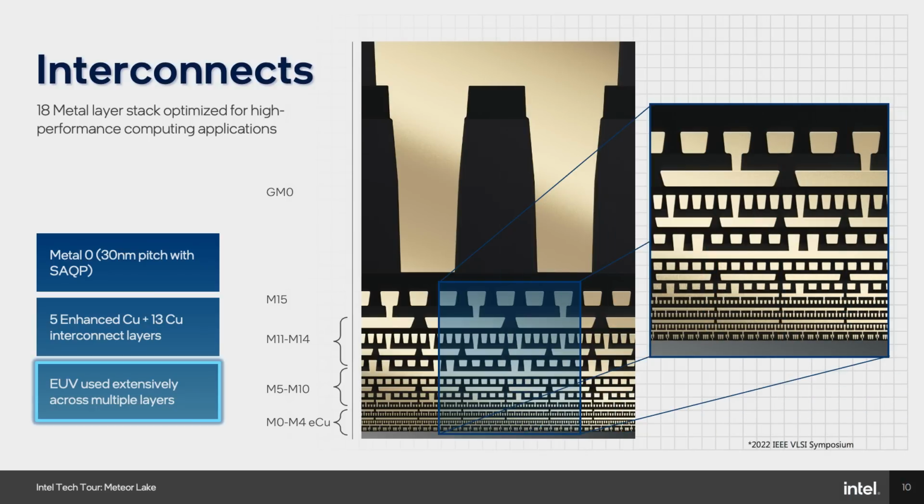The metal stack is 18 metal layers. Now we have a 0 metal layer, and then we have metal 1 through 15, and then we have these giant metal distribution layers up at the top. So it's 18 tall. You're also challenged by electromigration, right? Electromigration is when you're putting voltage or power on a wire. Sometimes that metal wants to move. And metal moving is not a good thing. Right? No.